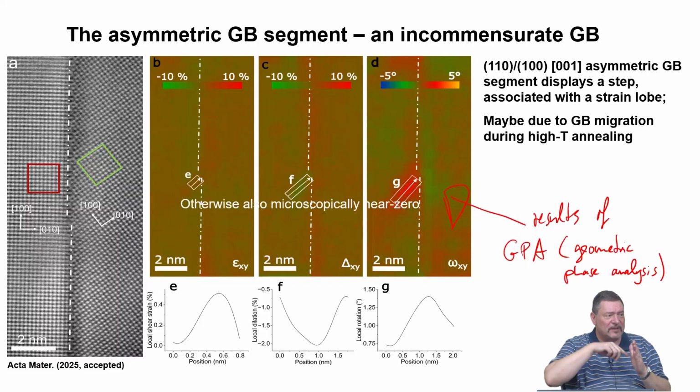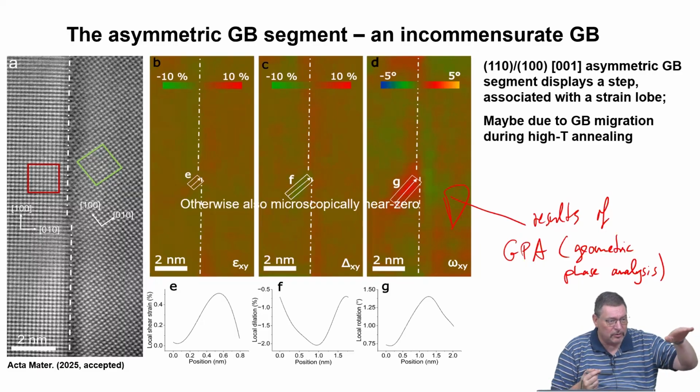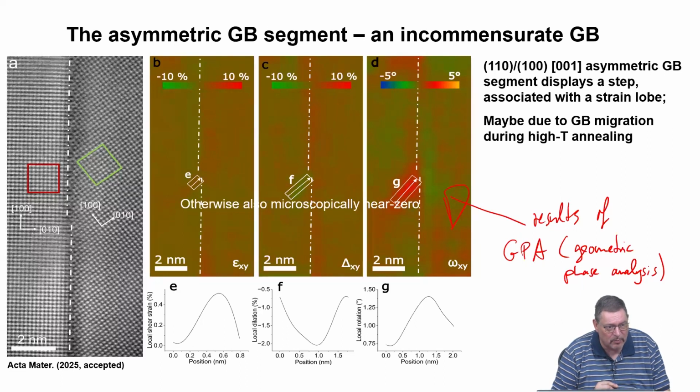So it calculates the Fourier components of the intensity distribution in Fourier space, then does the retransformation into real space, and you get these spatial color maps or heat maps, which are shown here, which show you for a given component of the in-plane strain tensor of the TEM sample, the distribution in space of these components. So color change means strain state change.